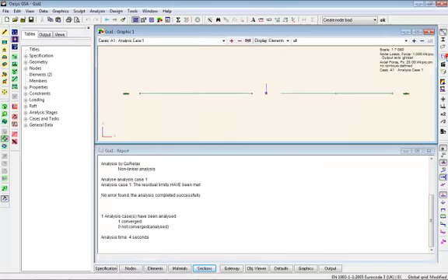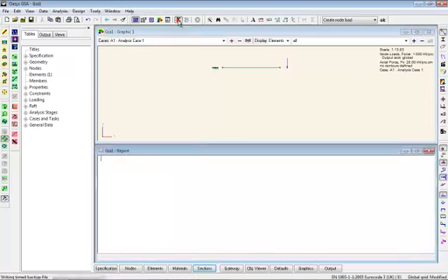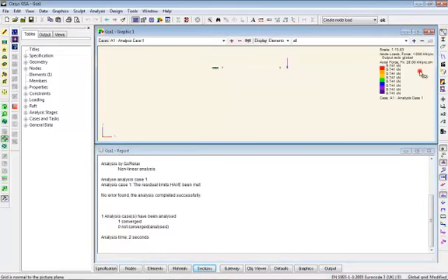Take another extreme example. Rather than the beam, if I just delete one half off and get rid of that spare node, we now have a pinned cantilever. If I rerun this analysis now, look at the deflected shape. You see, magnification 1, this mechanism has now swung down. It's now hanging straight down. This is now in equilibrium at the deformed position, not the original position, but as you can see, the deformed position is quite a long way from the original.